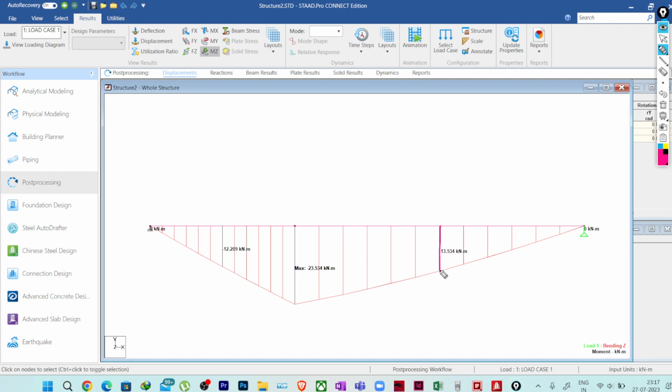Okay, so here at the center of this particular part we are getting this value. This is not required for us, we'll keep like this. Now if you ask me how I will be finding out the moment diagram and what is the moment here, you just have to take the derivative d/dx of the M(x). Taking x equal to 1, x equal to 2 in the M(x) equation, you can see what is the value coming, then you can find out the diagram accordingly.